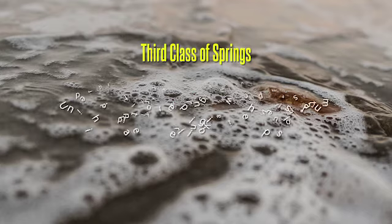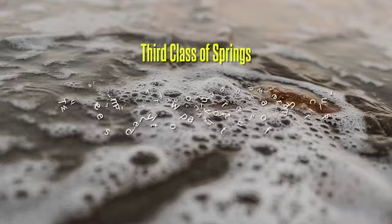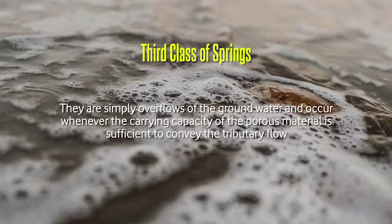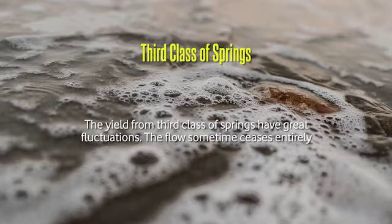Now, third class of spring. Under this category are springs in which the porous stratum in the vicinity of the spring is neither overlain nor immediately underlain by an impervious one. They are simply overflows of the groundwater and occur whenever the carrying capacity of the porous material is sufficient to convey the tributary flow. The yield from the third class of spring has great fluctuation. The flow sometimes ceases entirely.